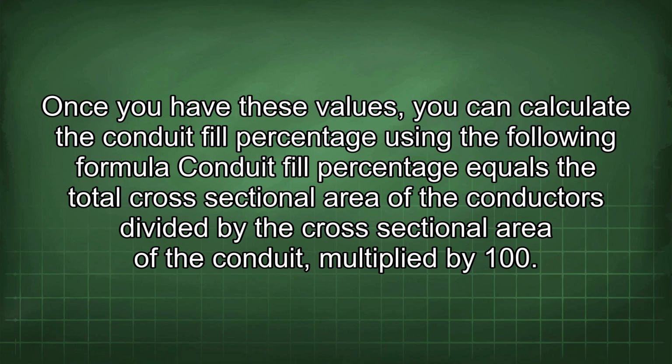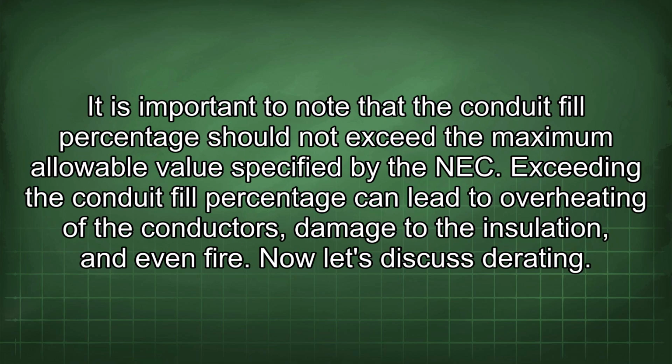Conduit fill percentage equals the total cross-sectional area of the conductors divided by the cross-sectional area of the conduit, multiplied by 100. It is important to note that the conduit fill percentage should not exceed the maximum allowable value specified by the NEC. Exceeding the conduit fill percentage can lead to overheating of the conductors, damage to the insulation, and even fire. Now let's discuss derating.